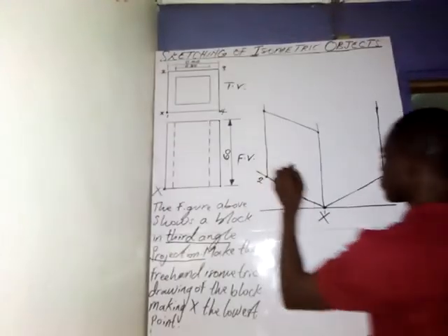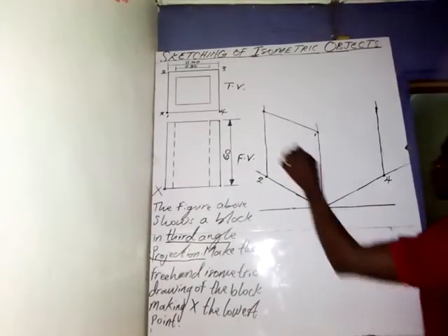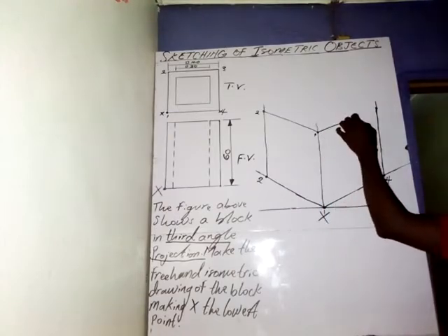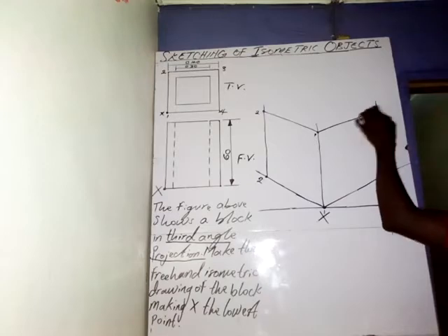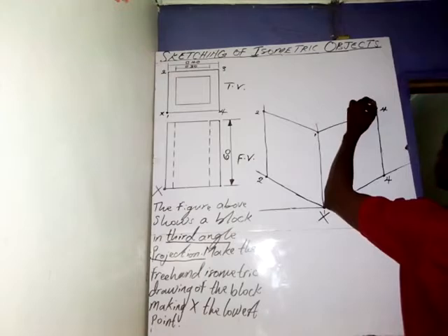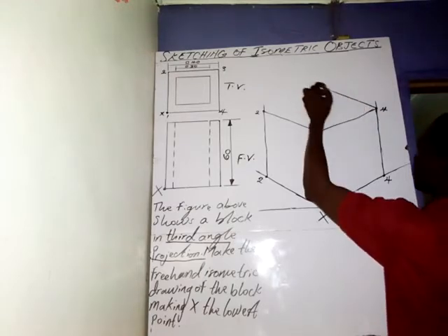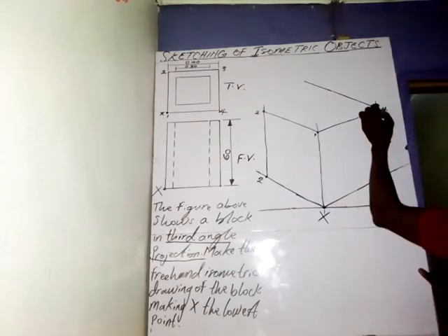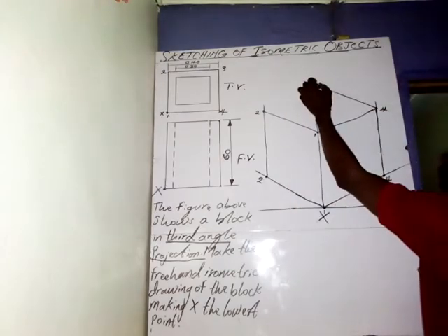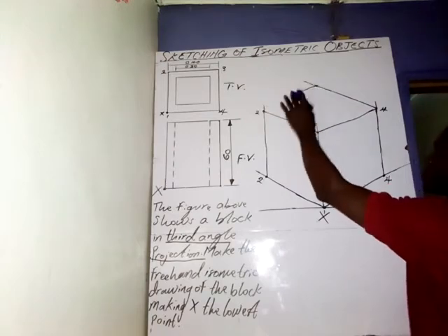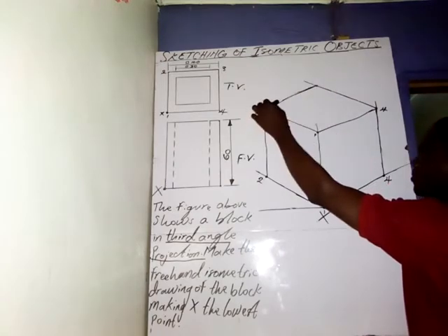Join this point together. So let's call this point 1 at the top. This is point 2 at the top. Then you draw this, join this together here. So this is point 4 at the top. Okay. Then the next thing is you produce a line in this direction, free-handed. Then take a measurement of 40 millimeters from here to here. Okay. Then you join this together like this.